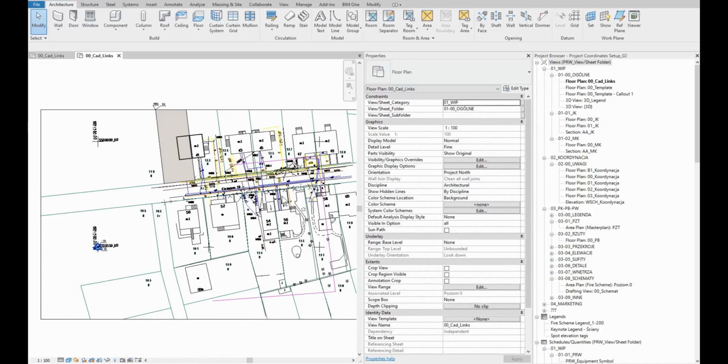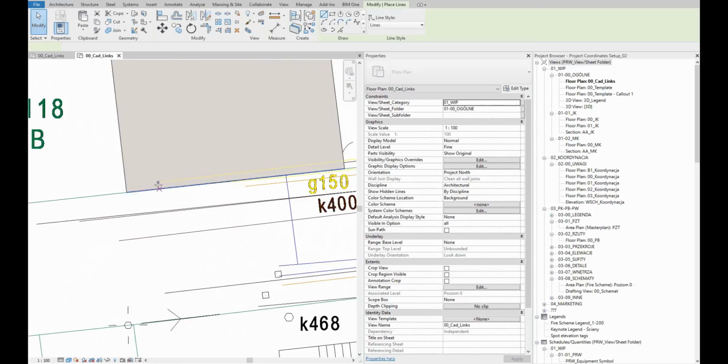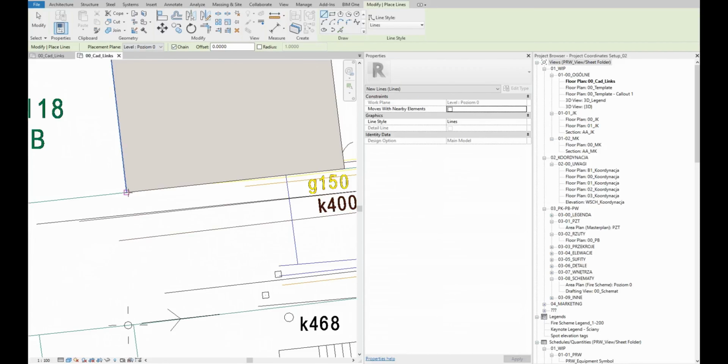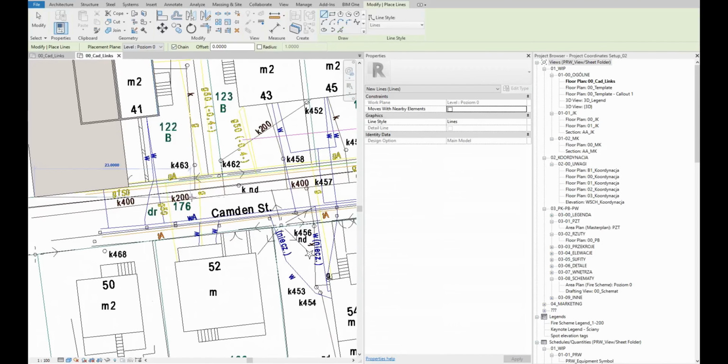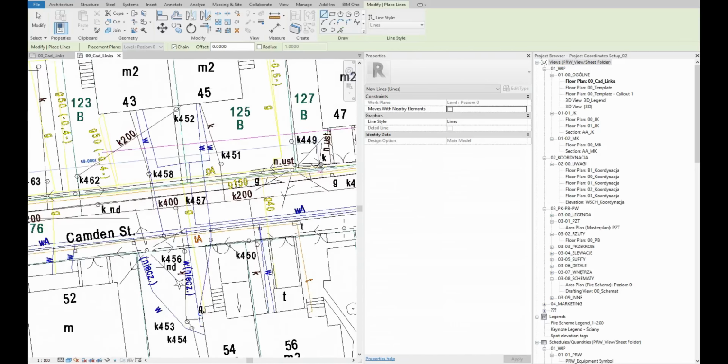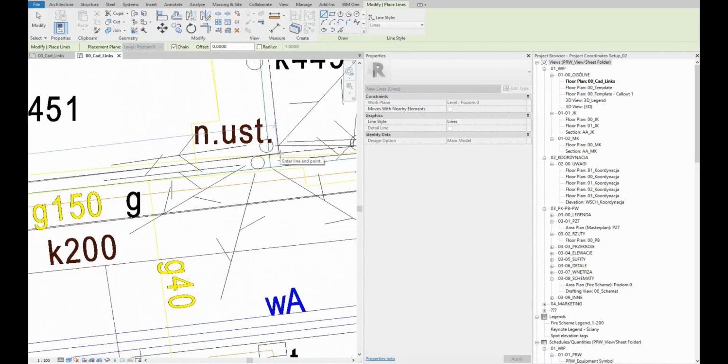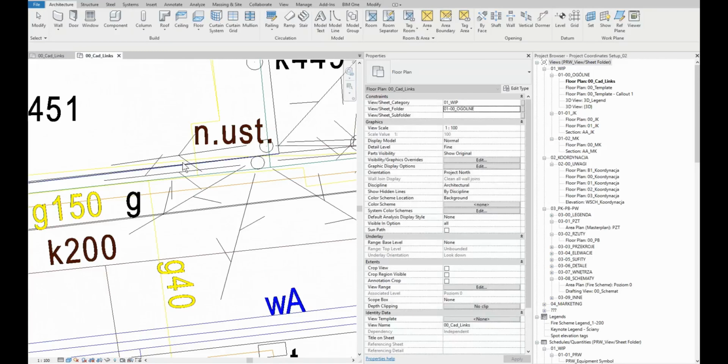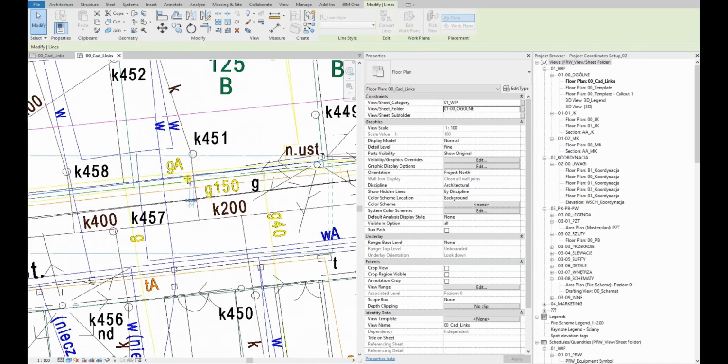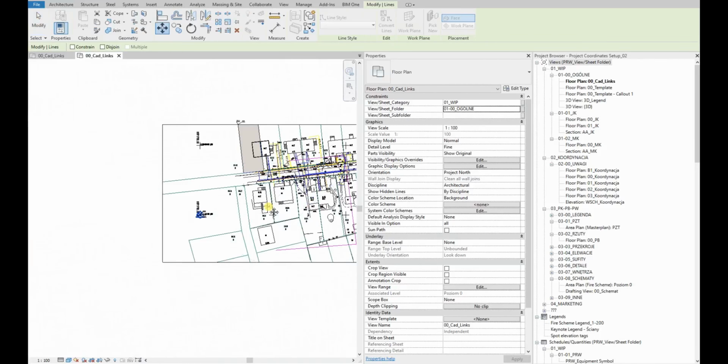First, we need to check the actual angle of the building, or primary grid angle. To do this, the best solution is to draw a line along, let's say, the street here. It should be as long as possible, going along all the plots to grab the actual angle. For this exercise, let's say this is more or less precise.